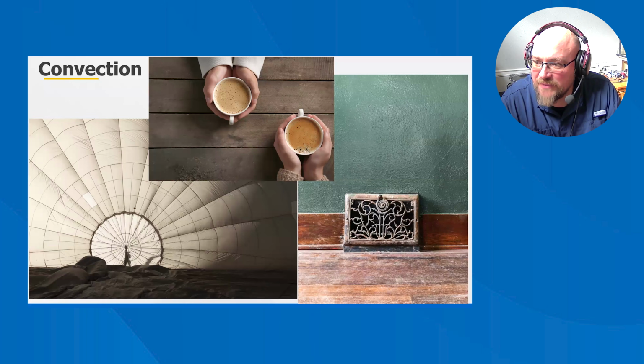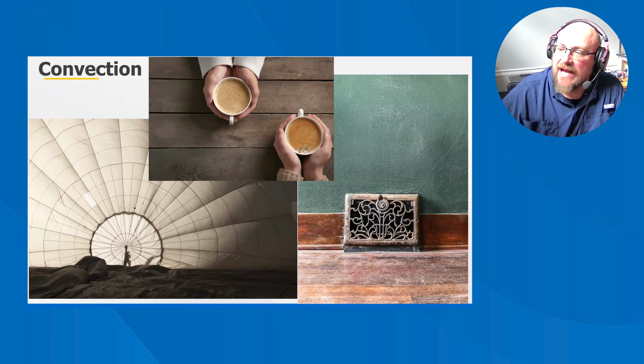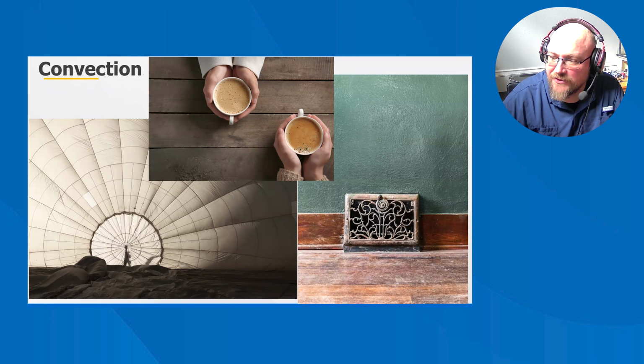Inside a wall cavity, there can be a convective loop where cool and warm air are moving around inside the wall cavity. If warm, moist air comes into contact with the cold surface of that wall assembly, then condensation may form inside the wall. As another example, an old gravity furnace heats the air.